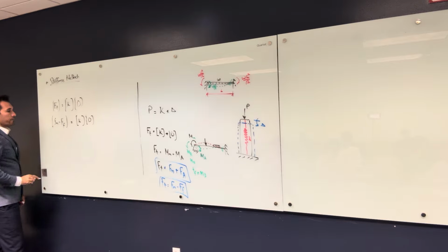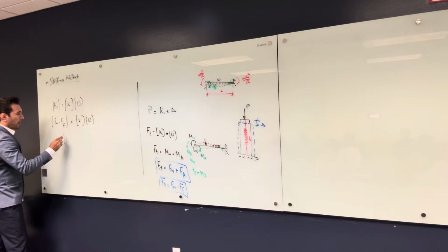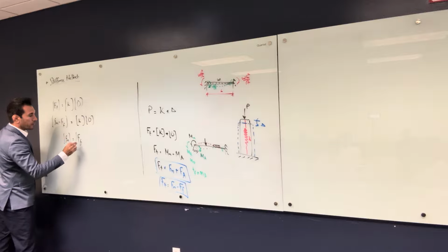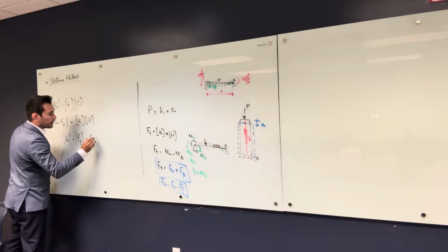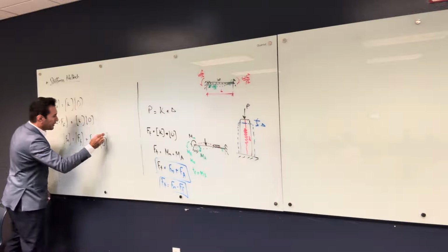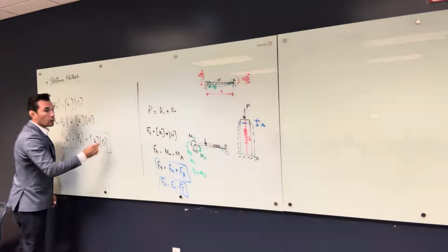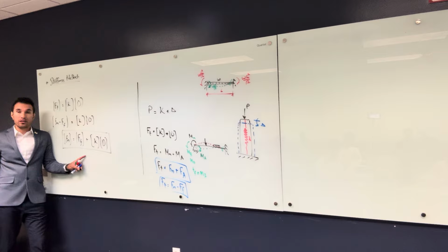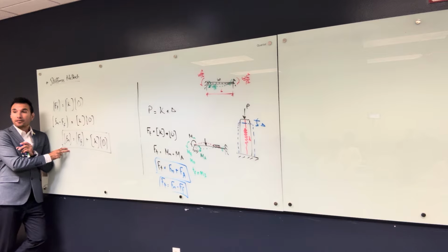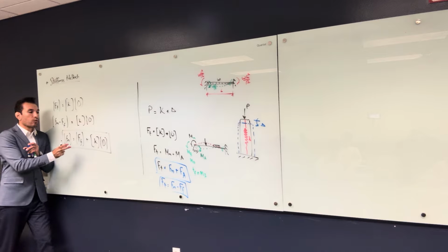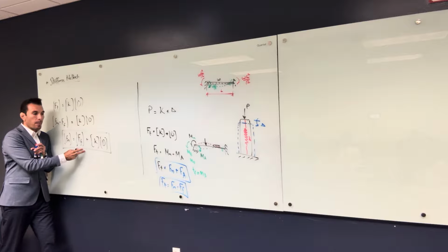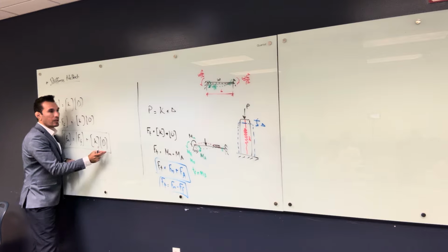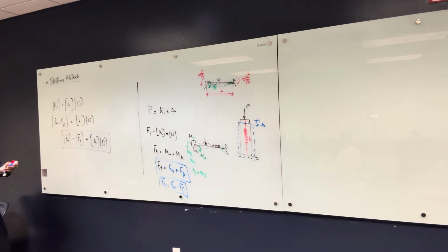So I can send F fixed end forces to the other side, and I can put the F nodal forces is gonna be equal to the F fixed end forces plus the stiffness matrix multiplied by the deformation D. That is the most important rule in the stiffness method. The most important one. Never forget this one. The nodal force at a node that has a degree of freedom is equal to the fixed end forces at this node plus the stiffness matrix multiplied by the deformation.